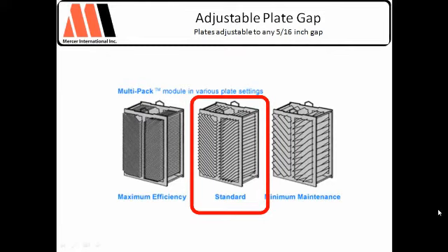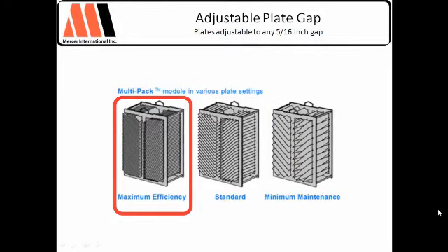Now, we do know that there are times where the wastewater characteristics will change, flow rates are going to increase, oil content's higher, or if effluent regulations change, if you're down to 5 ppm, and believe me, it's coming. We're shipping things overseas where the requirement's 5 parts per million now. They realize that the environmental thing's here to stay, and they're taking care of that. So in this case, we're able to get down to a 1/2 inch, which is a 5/16 right angle gap, and bring it down into that 45 micron removal. That's about as tight as you get in the industry.